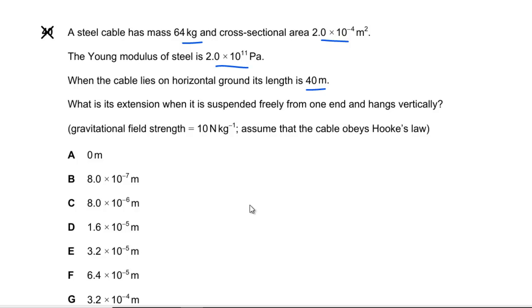Having thought about it in the past. Normally when we do Young's modulus, you get your material and lay it on the table and then stretch it. So we've got some kind of force that we're applying to a bit of material, and we're not concerned about the weight of the material because we're just stretching it sideways. So they're trying to throw us off our guard here by saying, okay, let's have it hanging downwards because the weight of the material itself is the thing that's stretching it.